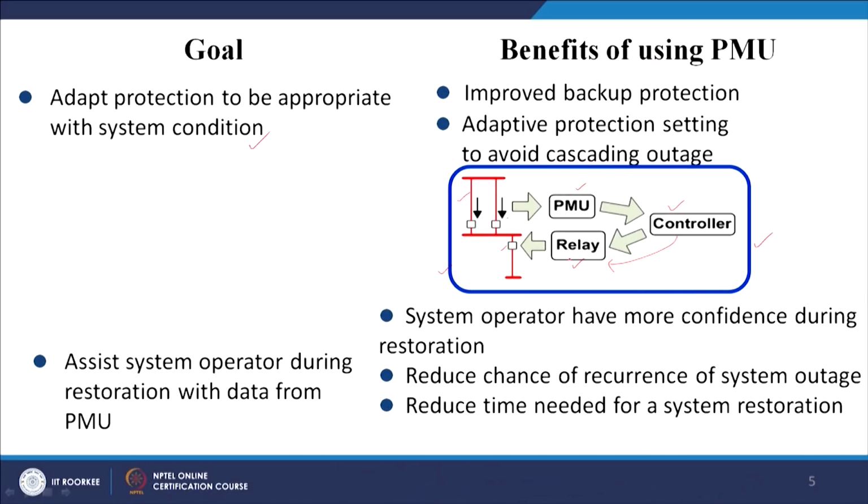If we talk about digital relays, we are just adding this PMU information as far as the WAMS technology is concerned, because to make the relay more intelligent and smart, we can provide more information globally. It is a local device. The relay only takes care of the voltage and current information at the bus where it is located. But if I can take the information from other buses with the help of the PMU, which is a very important component of WAMS technology, then those data will be really helpful for the relay to take other necessary actions.